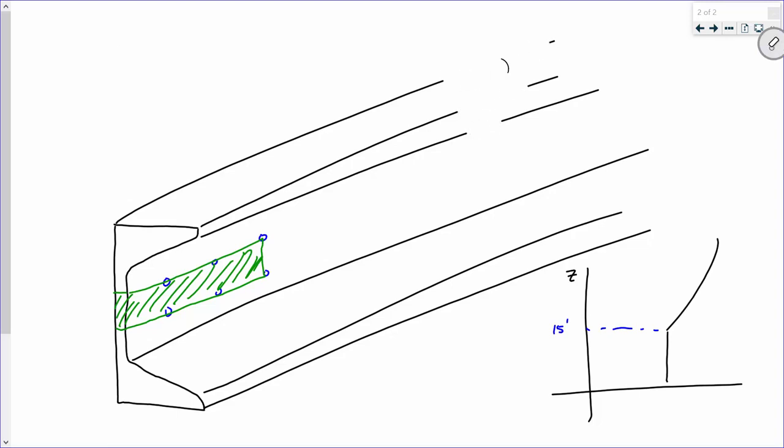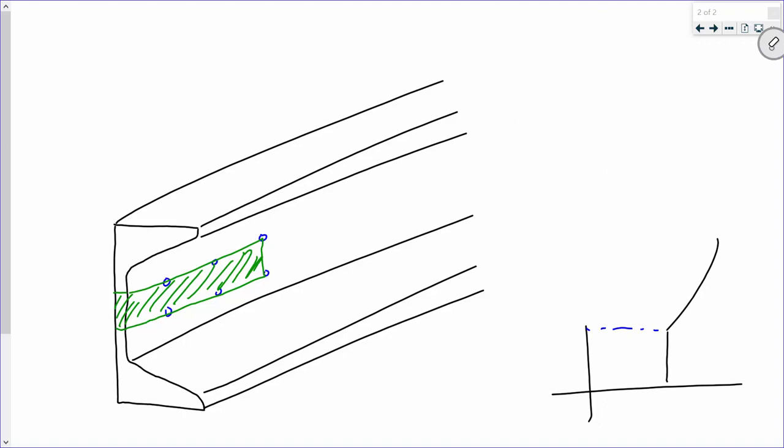So, here's the channel, right? And it's being yanked on like this. First off, when we're talking about AGT and AGV, we're talking about the paths that are inside the channel. So essentially this one, and this one, right? Makes sense? Because the bolts are going to transfer that load to the members. So this is really what I'm interested in. Sound good? All right. The point really to look at is, see, this arrow is showing how the member is being loaded. I'm yanking on it like this.